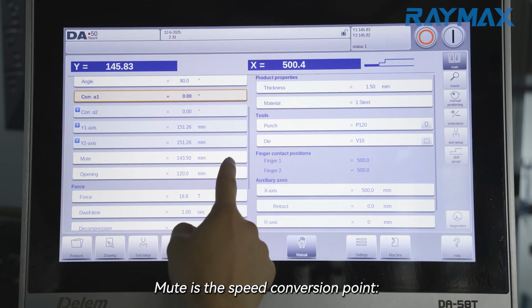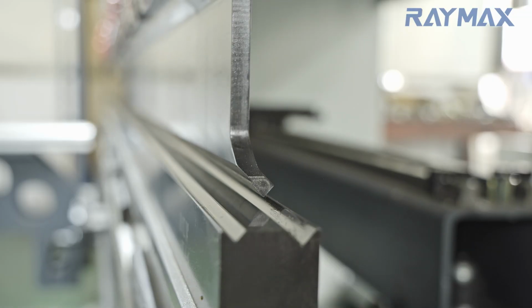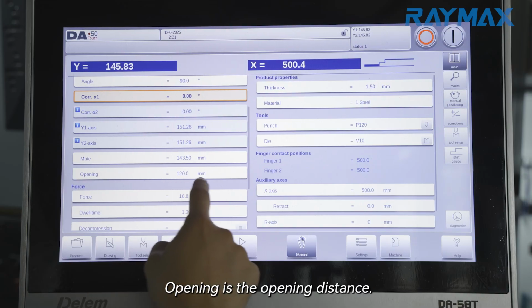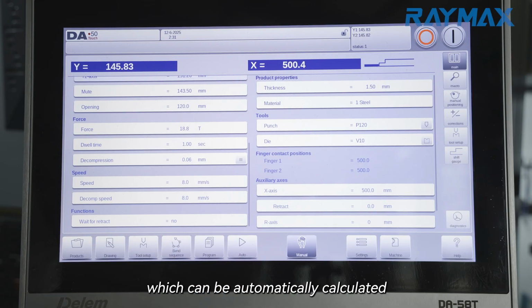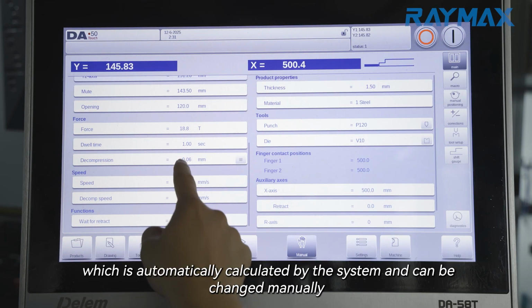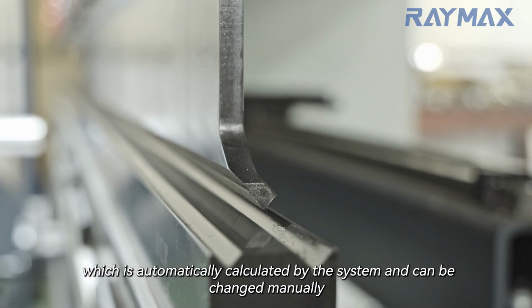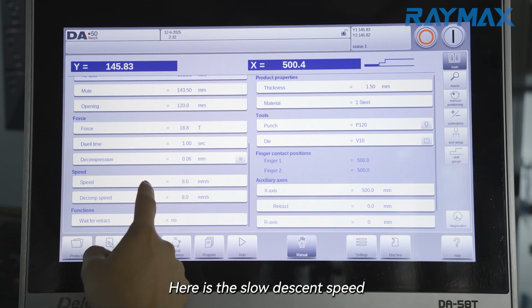Mute is the speed conversion point, the conversion point from fast descent to slow descent. Opening is the opening distance. Force is the tonnage, which can be automatically calculated by the system or changed manually. Dwelling time. The unloading distance here is the distance of slow lifting, which is automatically calculated by the system and can be changed manually. Here is the slow descent speed.